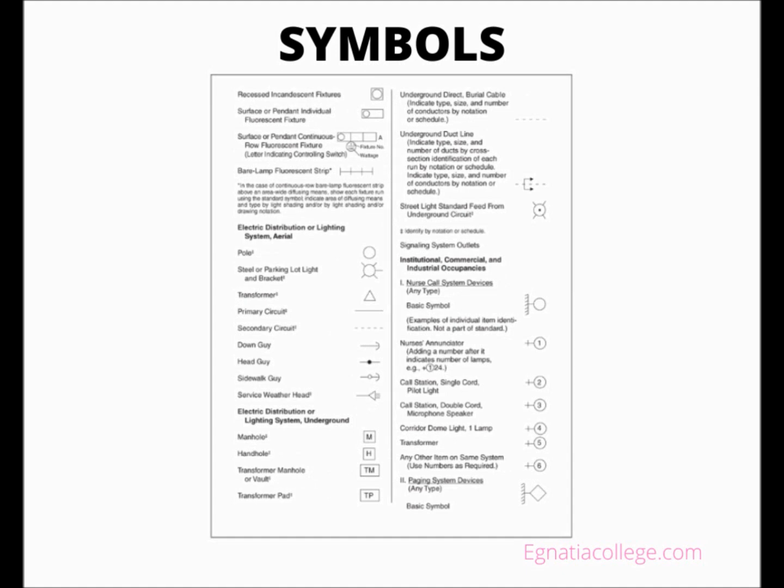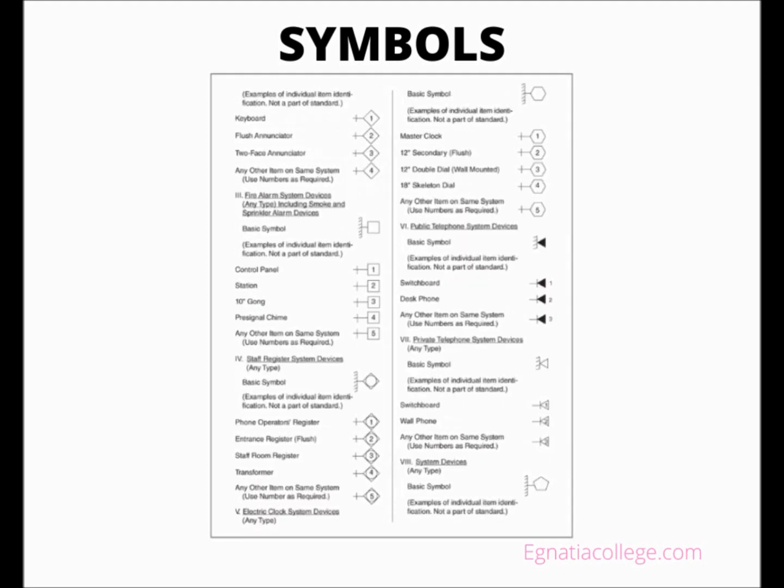Learning the basic form of the various symbols is the best starting point in developing the ability to interpret the drawings and the related symbol meanings. This figure shows common electrical symbols and abbreviations. The school edition drawing E1, symbol legend A4, contains an electrical symbol list for the project. From the symbol list, it can be seen that there are duplex receptacles, switches, telephone outlets, special purpose outlets, and fire alarm devices mounted at various heights.